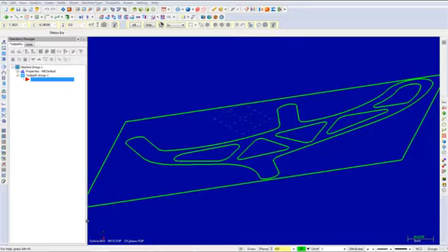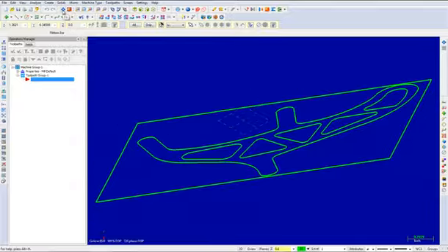Select the fit icon to view the entire geometry. We will now create a new view. In this step, you will learn how to create a new view from the flat part geometry. To define a plane, you can select two intersecting lines, a 2D entity such as an arc or flat surface, or you can select 3 points. That being said, from the ribbon bar, select Planes, and then choose Planes by Geometry.